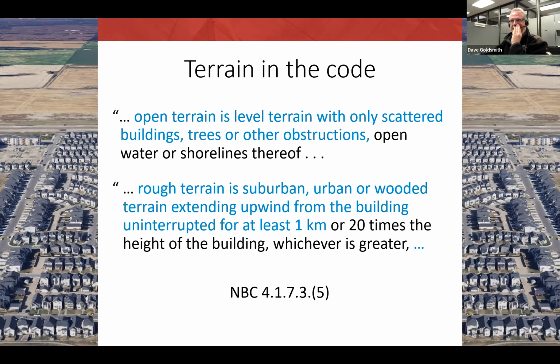The specifiers tend to be very conservative, and building envelope engineers tend to be very conservative, and they don't want to hear nitty-gritty arguments that would reduce the requirement. But that might not be the best thing for the customer on some jobs where it really isn't warranted to use the full 1.0 when 0.8 might be the intermediate terrain calculation result.